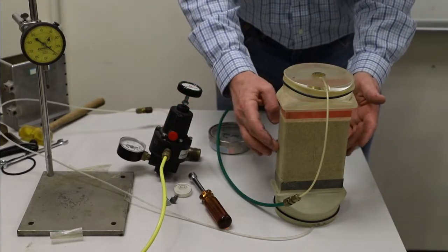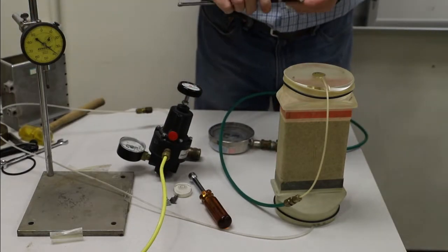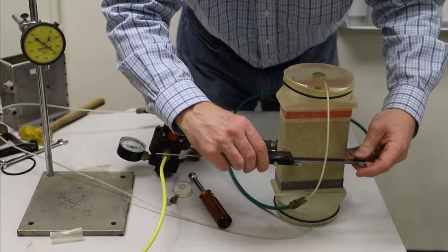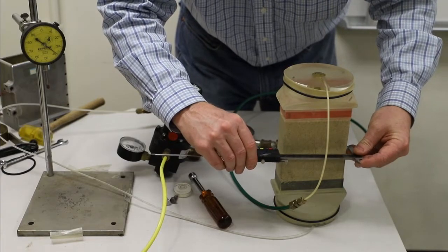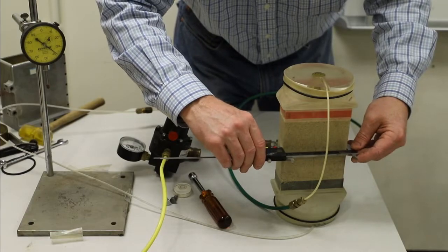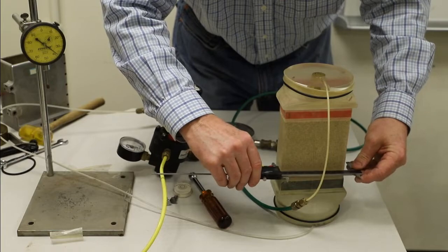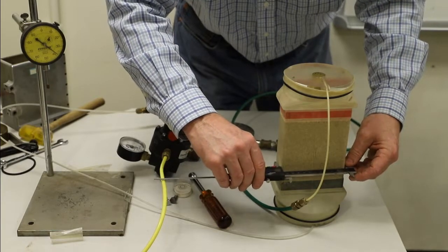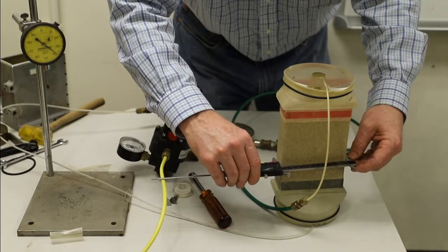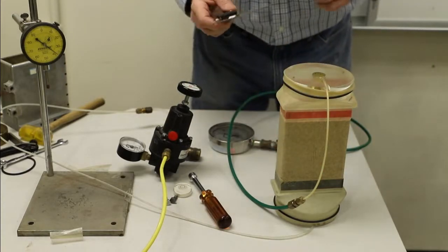Measuring the cross-section based on the rectangle, of course, is relatively straightforward with a dial calipers. This is a digital calipers, right? We could put that across the specimen in a few places and read off values. Okay, so that's what we do. We want to do that in a few places, again with height, because it could change a little bit. You want to check and make sure that you're relatively level, right? And we can do that for the broad length or the narrow length.